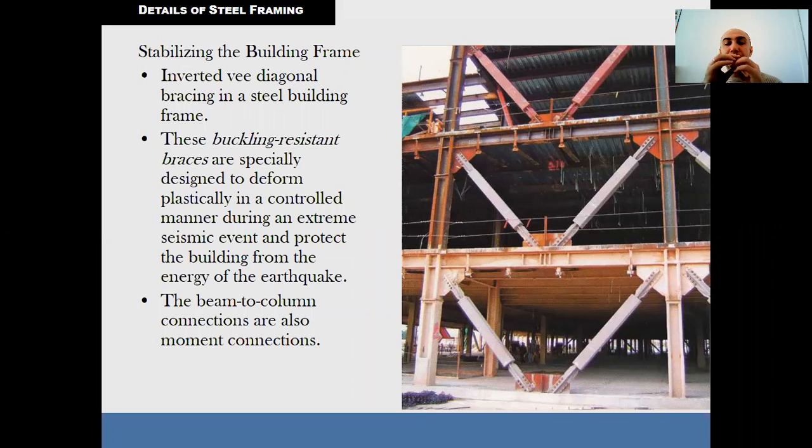It is typically made of, sometimes, concrete filled steel tubes. The design criterion is for the casing to provide adequate lateral resistance, meaning rigidity against the steel core buckling.